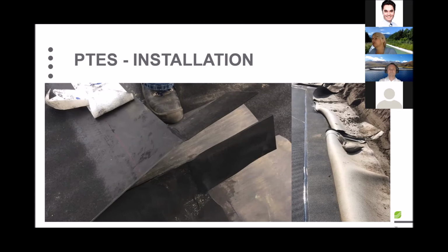And the right picture just shows how an extrusion weld should look in such an application. It should be even, it should have no grinding at the edges, it should not have a lot of excess amount at the outer sides of the seam, and the surface of the seam should be even and leveled.